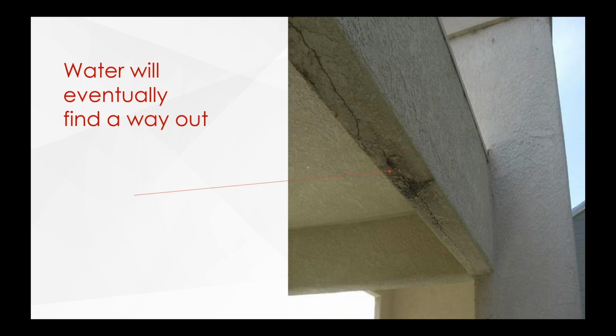Okay, and this was a photo of what that looks like. Again, they used a reinforced corner here. You don't see a soffit drip on there. Not a lot of water. This isn't that big of a panel, right? But look at it, it eventually made its way out, but it cracked all along here. So if you had some place where the water could escape in this corner, you would avoid that altogether.